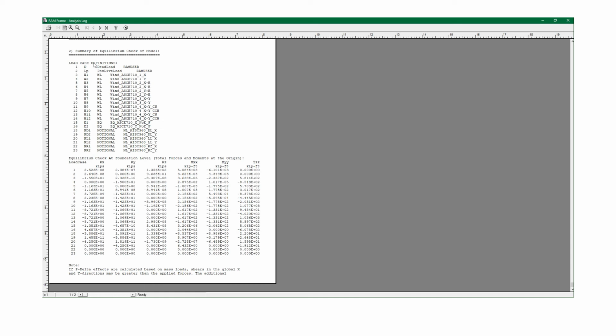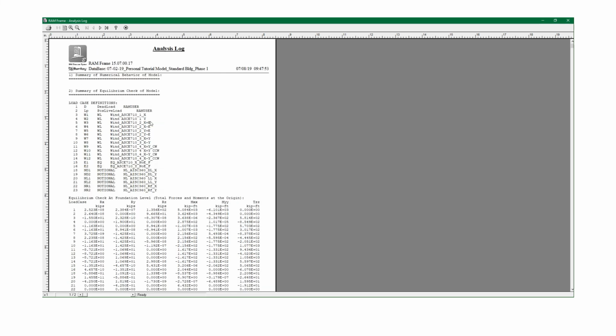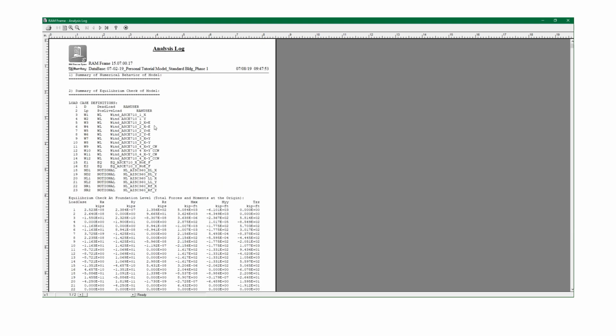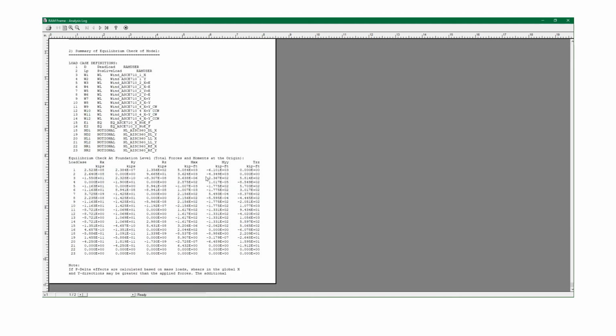All right. Same thing with our live load. Again, it's just going to give me the numbers on the lateral frame only, and it's only calculating 96 kips on the lateral frames. So that's something to be aware of. This analysis log is really the analysis log of this module, and that means the elements that are created in this module as lateral frame analysis. Other things you'll see here are the wind load in the X or wind load in the Y.